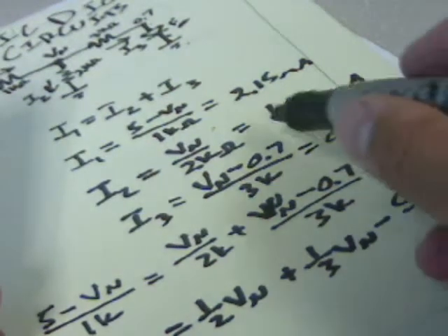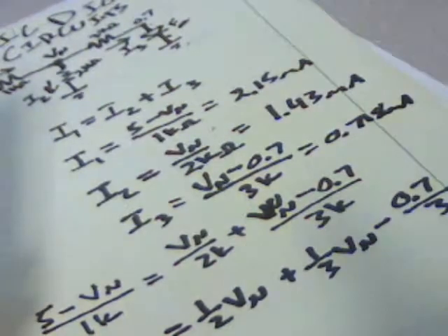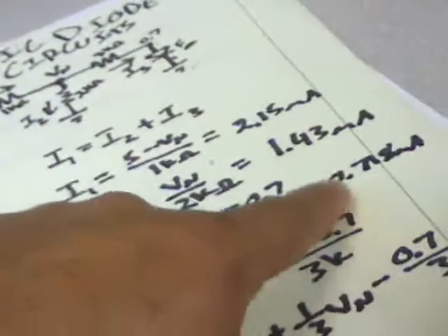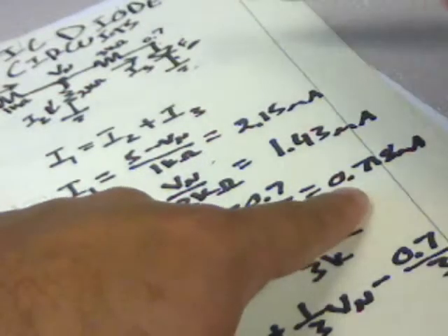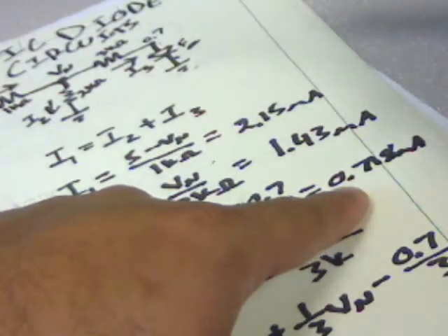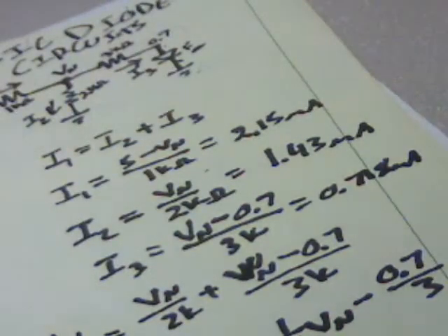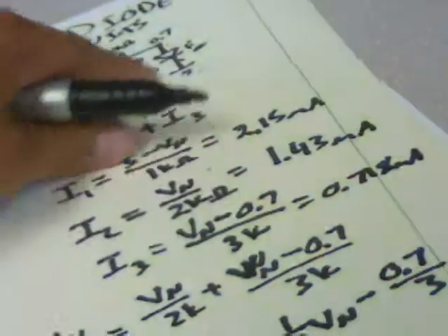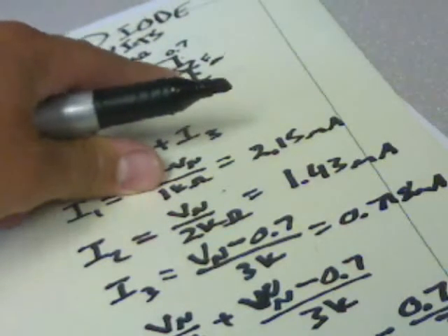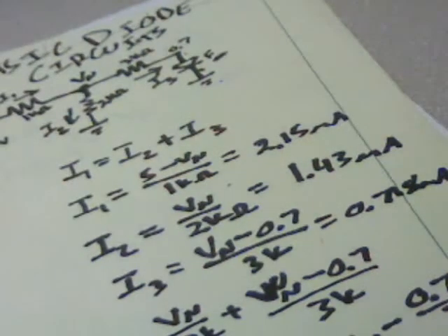And so we found all of our currents. We can note that there's no negative signs there, and so we have the proper circuit. Again, if we would have had a negative sign on this one, we would have known that we made the wrong assumption, and we would have had to start over. Alright, on the next one, maybe we'll do one that is in the wrong direction, is reverse bias, but we're going to assume it's forward bias, and we can see how that works.